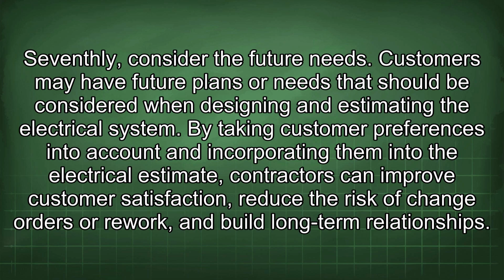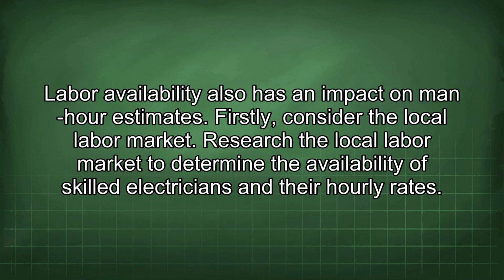By taking customer preferences into account and incorporating them into the electrical estimates, contractors can improve customer satisfaction, reduce the risk of change orders or rework, and build long-term relationships. Labor availability also has an impact on man-hour estimates. Firstly, consider the local labor market. Research the local labor market to determine the availability of skilled electricians and their hourly rates.